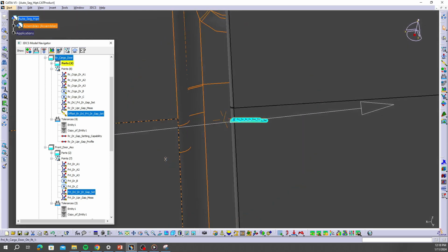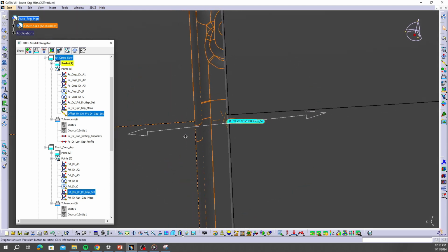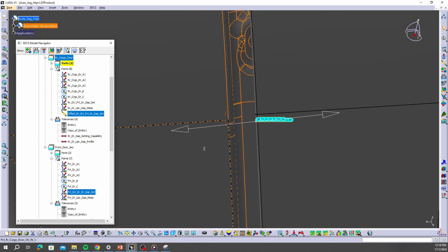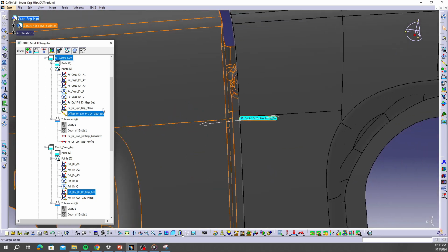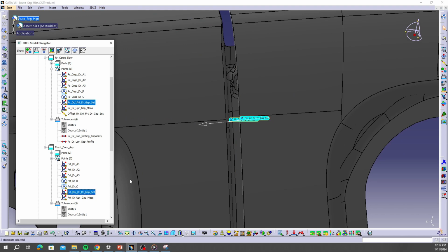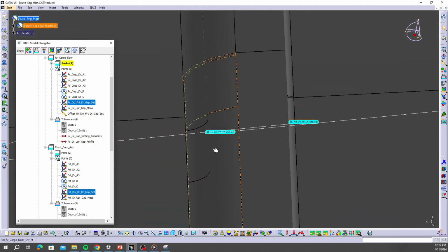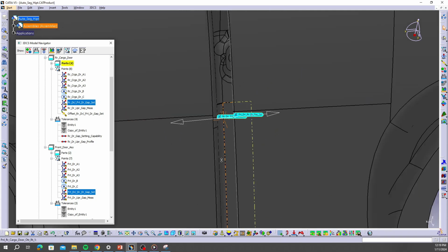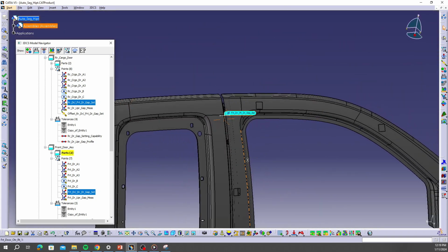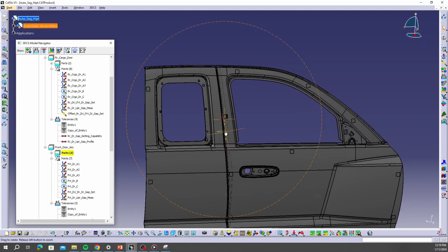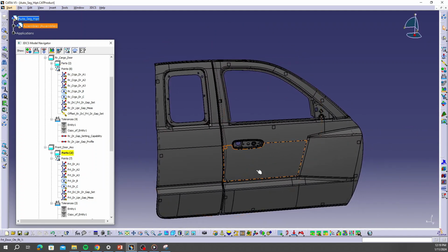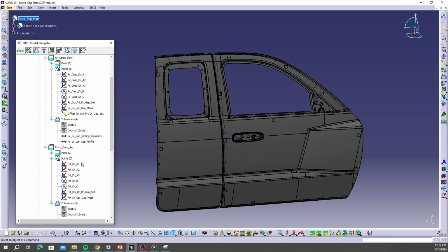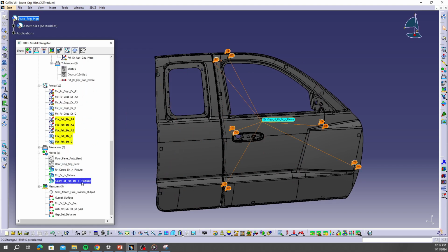It's something to be cautious of, and the reason being is that if your points are on the same plane or they're coincident, you won't get a mean shift. But if I were to use just these 2 points here and here, as you can see, there's a distance between them. The move operation will try to bring the points together, and you'll get a mean shift that's not there in the real world. So it'll be different example to example, but just make sure in a case like this, you need your points to be at least on the same plane so you don't get a mean shift.